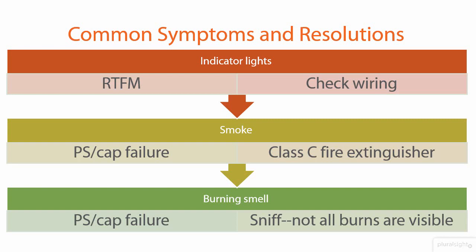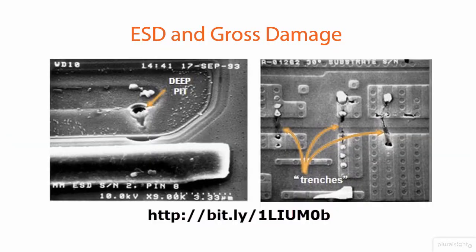Now, as far as repairing this kind of problem, boy, this can be a real big issue depending upon how the damage has spread on the motherboard. If it's a blown capacitor, in fact, I have a picture that I'm going to show you in just a second, you may or may not want to attempt replacing that component yourself. First of all, electrostatic discharge. We've covered this earlier in the course, in the hardware course, but remember that ESD refers to the transfer of electrical voltage, not through a circuit, but directly from object to object. And I mentioned that microelectric components like you find on your motherboard can be damaged by levels of voltage that you can't even feel.